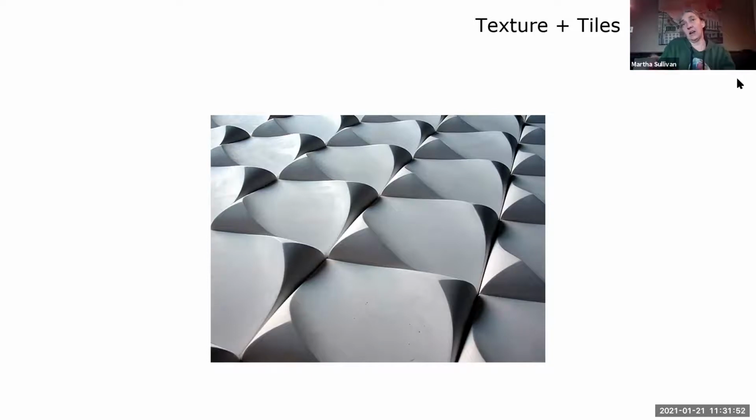And beyond that, they become more important when there's some sort of thermal load. So bricks that would be specific to the outside of a building may not be the exact same bricks in all cases that you would use around a fireplace or someplace that had a heat sensitive area. That would be especially true if you were building something for an industrial setting. So not all bricks are created equal when it comes to their refractory materials, right?